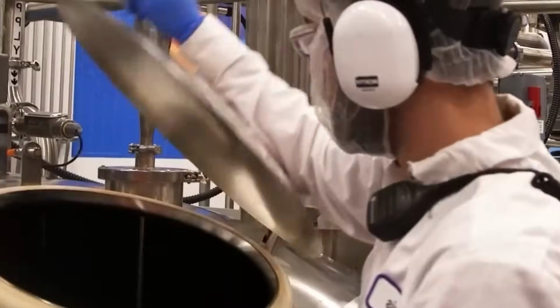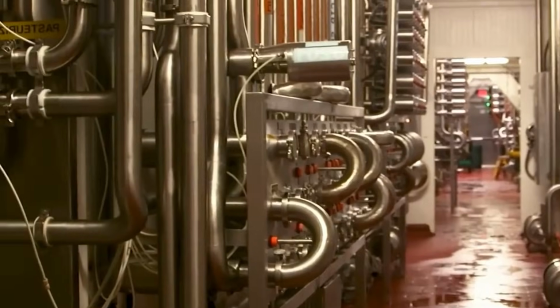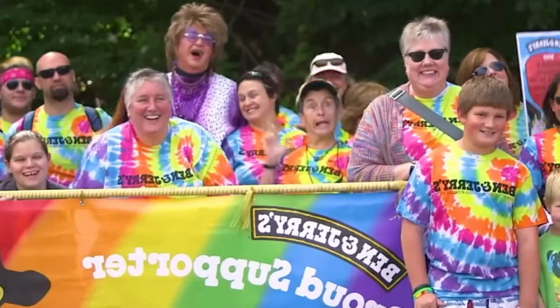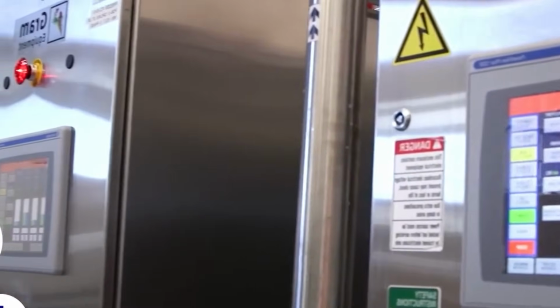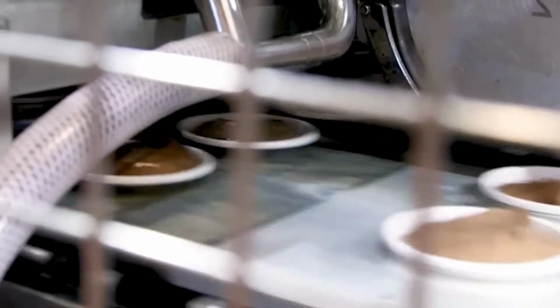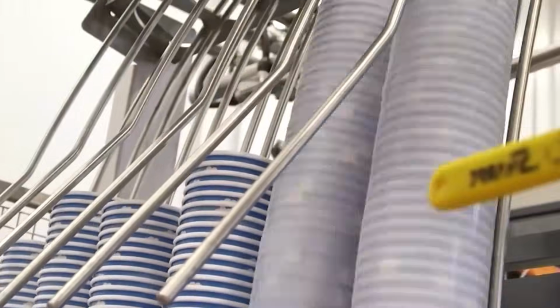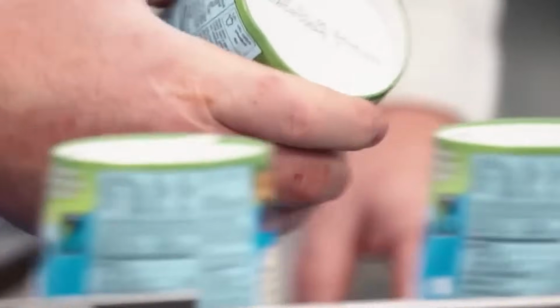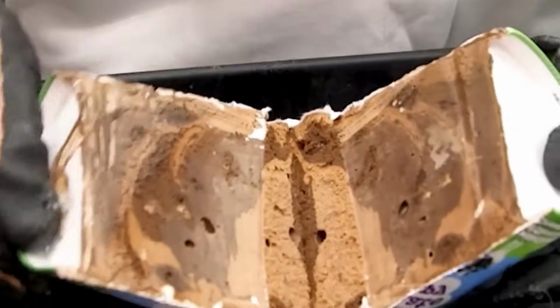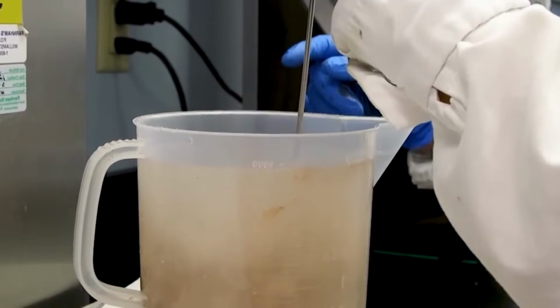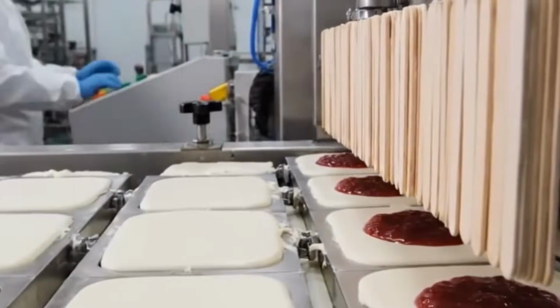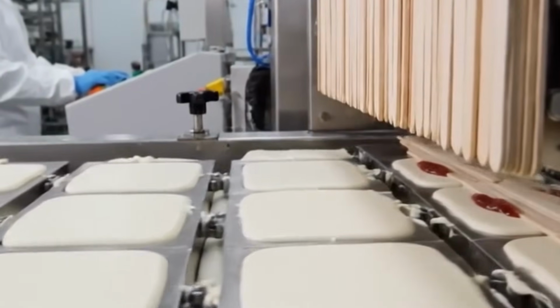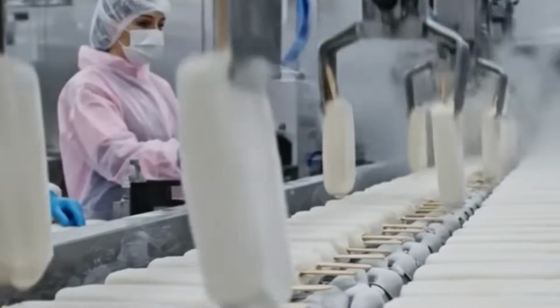For bulk containers, the ice cream is extruded directly into tubs or pails using piston or rotary fillers. For single-serve novelties or molded formats, the product enters downstream portioning or molding stations. In extrusion-based forming systems, the semi-solid ice cream is extruded through stainless steel nozzles onto a moving stainless steel belt cooled to 40 degrees using cryogenic cooling elements.